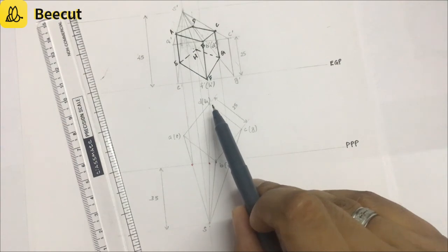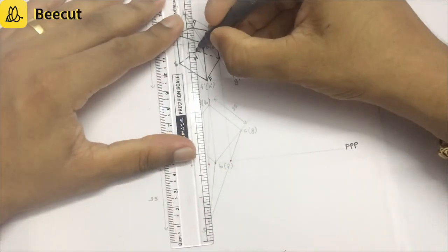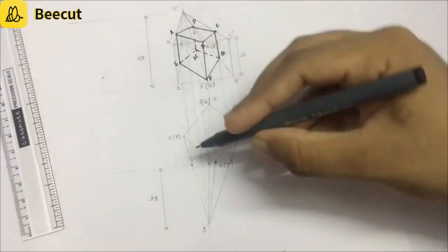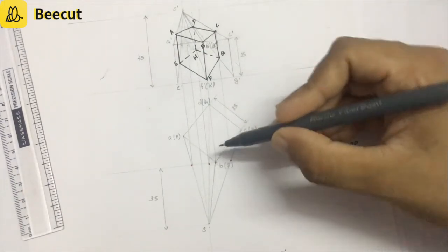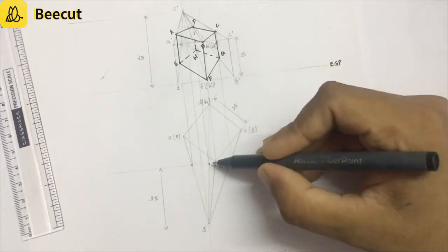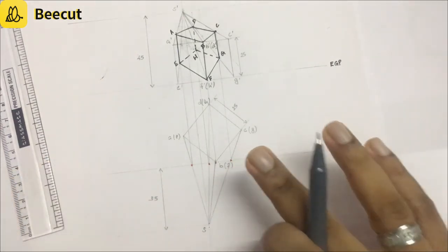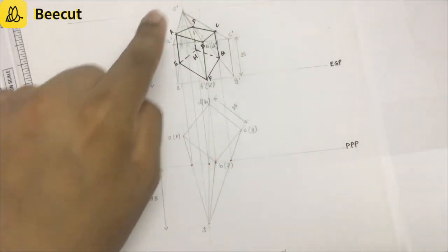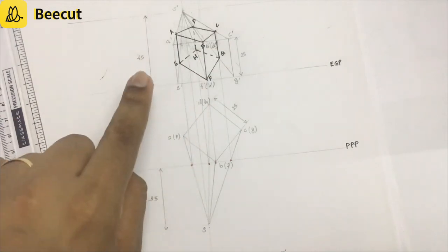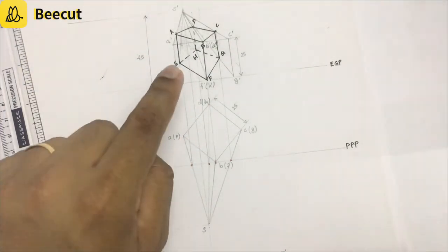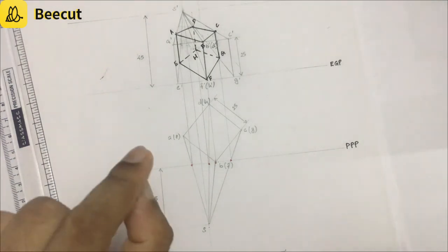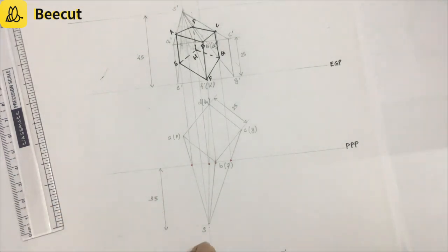So it is evident that two different lines, this particular point and this line, are completely visible. This and this are not visible. This visibility is to be considered only after drawing the outside edges. After drawing the outside edges, you then look at the internal edges, whether they are visible or not visible. For doing that, you have to look from here. So that's how the perspective view of the cube is to be drawn. Thank you.